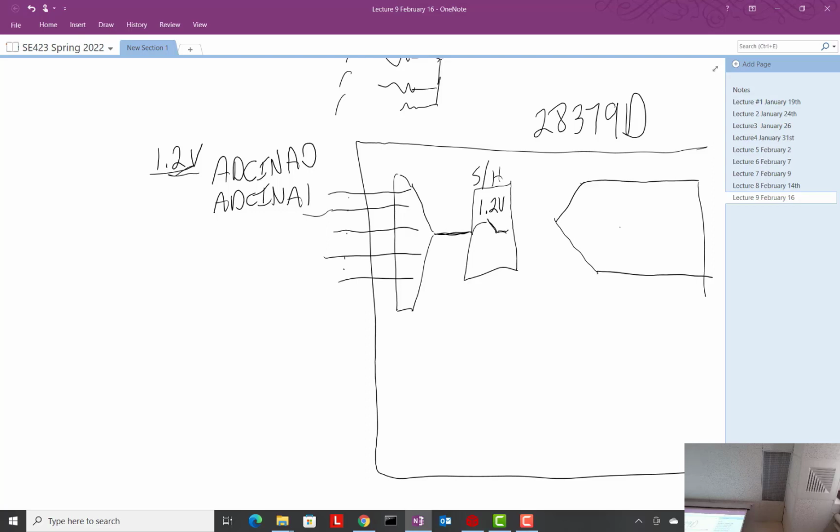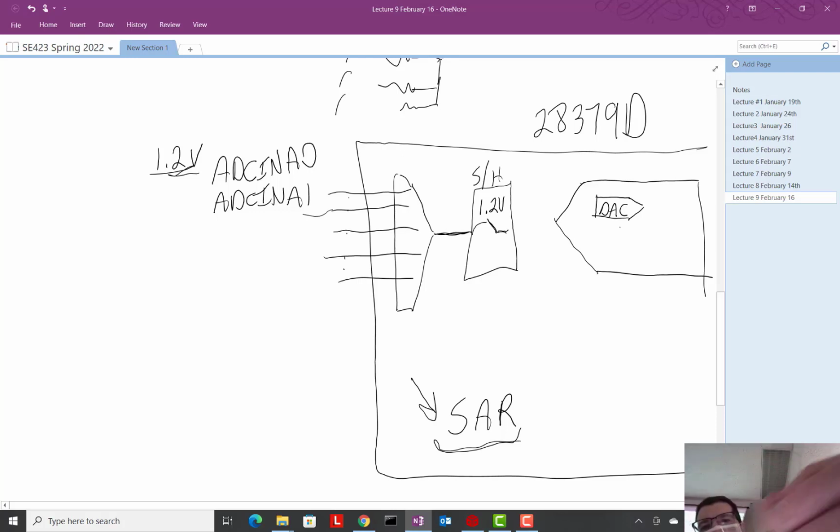And how does the conversion work? This is kind of fun. What we have inside the ADC is, as I said, a DAC. It's a 12-bit DAC also, making this a 12-bit ADC, and I'll explain. This type of ADC is called a Successive Approximation Register, if you're interested. These are the fastest ADCs. There are a number of other styles of ADCs that are usually a little slower, but these are probably the most popular because they're so fast. So we've got this 12-bit DAC.